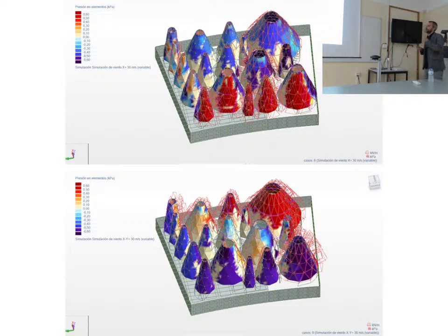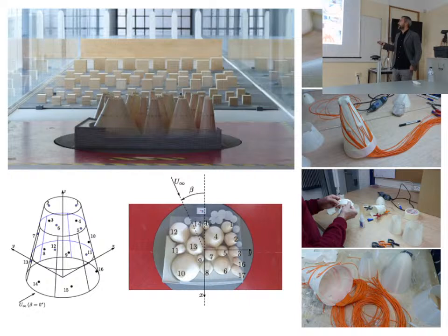We began with these numerical models for the wind loads. The governing load here was the wind load, of course, on the cones, and this is not a very easy geometry, also with this position, one after the other, and how to evaluate wind loads in these kinds of structures. So we began with this kind of analysis, and then we also did wind tunnel testing for having more accurate values for the wind loads.